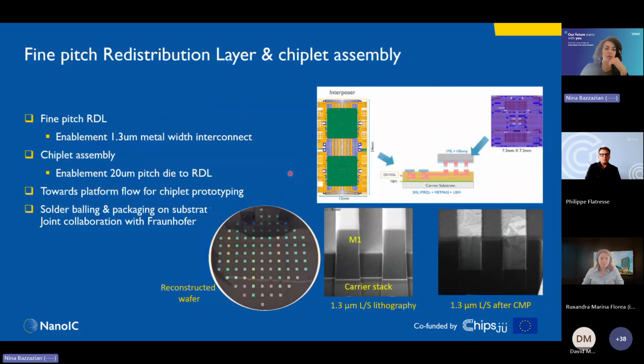And the final technology I would like to discuss is the RDL, Advanced Redistribution Layer Technology. This is another approach for combining multiple dies into a single system. Here, unlike the hybrid bonding, an intermediate interconnect structure is created. As shown here in this cross-section, this yellow part, an organic patterning layer is deposited, for example, a resist, and then filled with copper through a Damascene-like process, and then, of course, CMP'd.